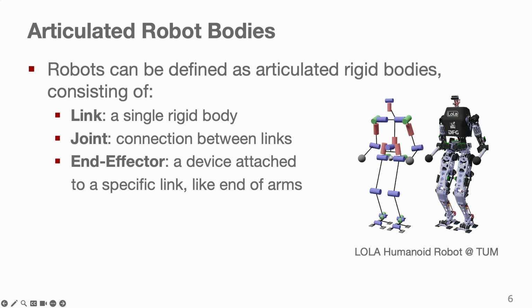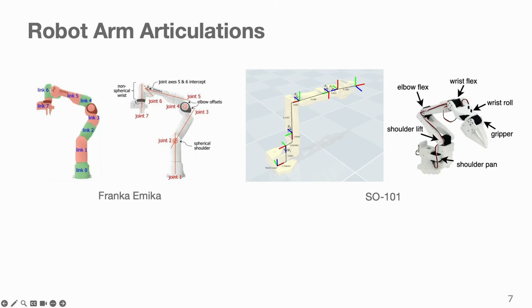And the key takeaway here is that an articulated robot is essentially just a chain of coordinate frames. So everything that we just covered, how to convert and chain all these matrices, you would do this to find out, for example, where your hand is relative to your humanoid robot's frame. You can just multiply and chain these to do these computations.